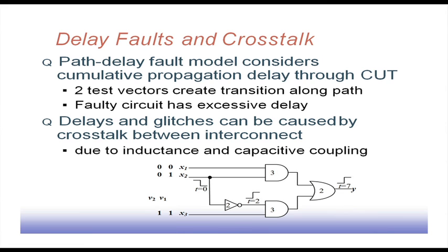Another class of faults are known as delay faults, and there is also something called crosstalk. Delay fault means a circuit functions properly as far as its function is concerned, but the timing is a problem: it does not produce the output within the desired time. This is a problem because if the output of a certain stage of logic does not come up within the desired time, then when that output is fed as input to the next level,